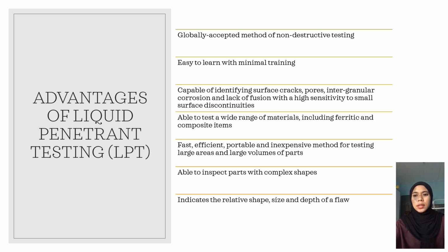For advantages, it is easy to learn with minimal training. It is also capable of identifying surface cracks, pores and small surface discontinuities. It is able to test a wide range of materials, including very thick and composite items. It is also a fast, efficient, portable and inexpensive method for testing large areas and large volumes of parts. And it is also able to inspect parts with complex shapes.